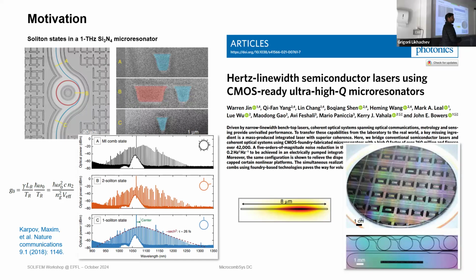Whereas if you want to design low noise on-chip lasers, there you actually don't want any four-wave mixing happening. You don't want any parametric oscillation. You don't want any frequency combs. You want a low noise single frequency lasing. So there you don't want to exploit the Chi3 properties of the material, so you design low confinement waveguides.